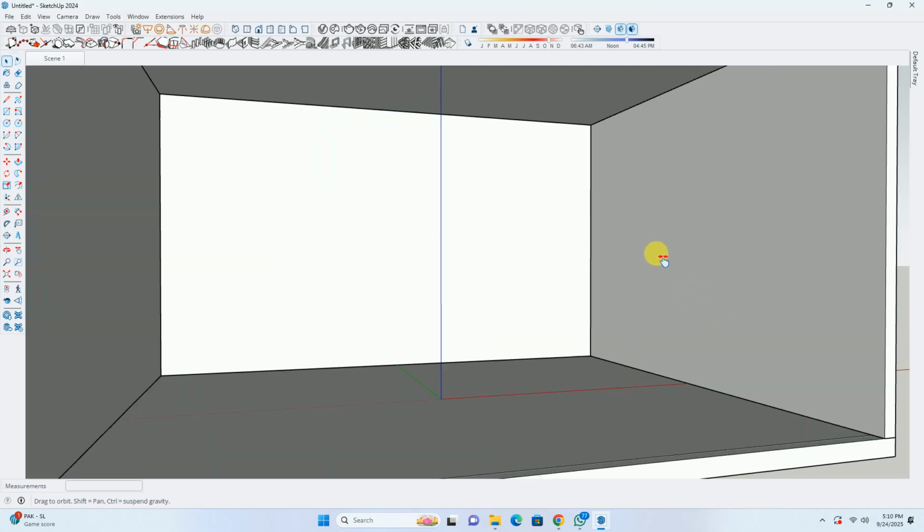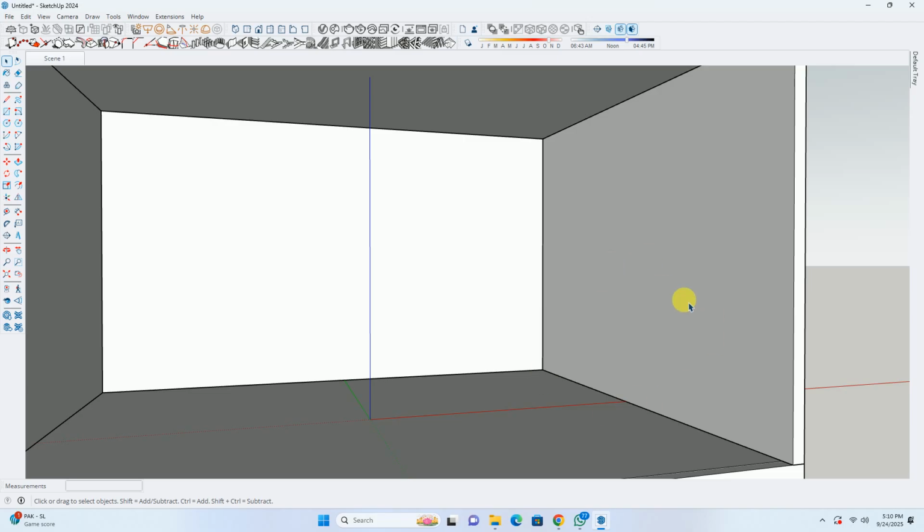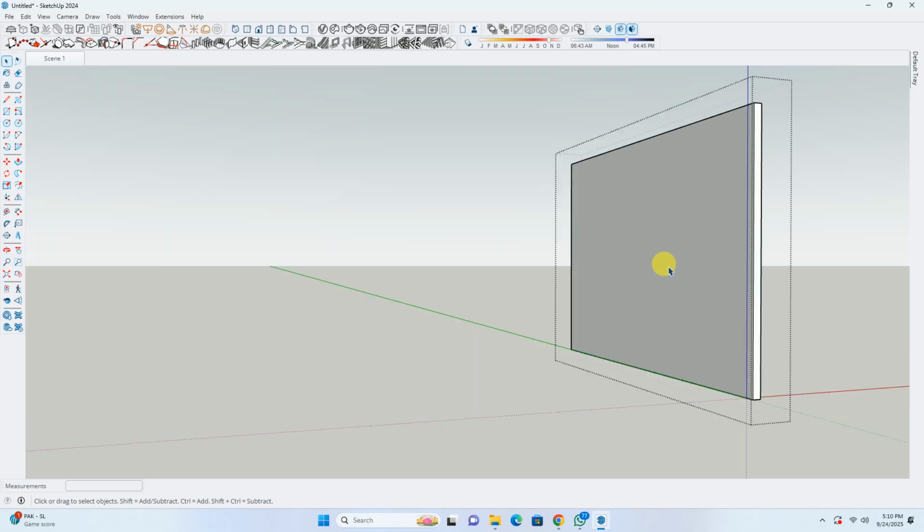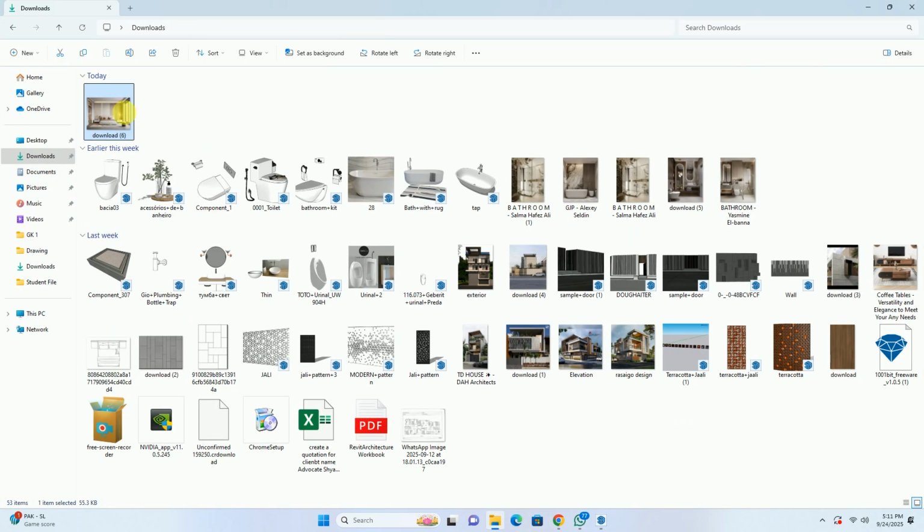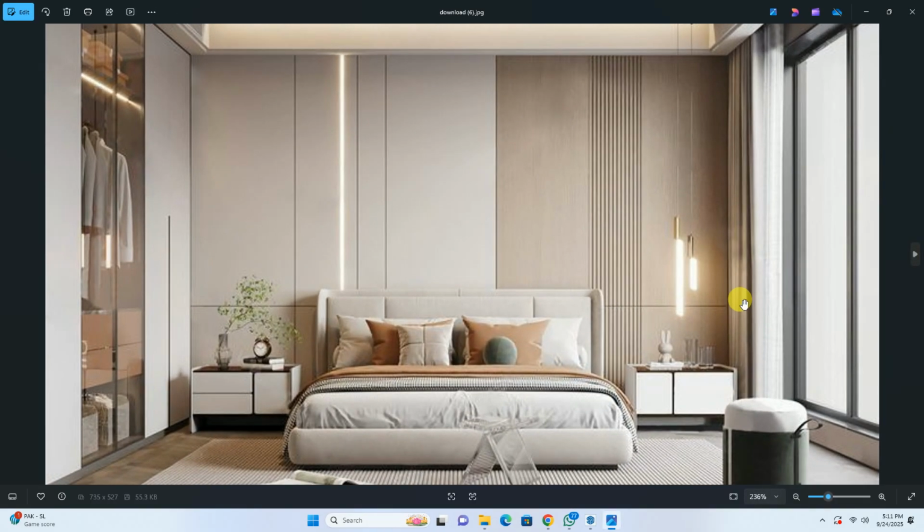Okay. So we want to create a window on this wall. We'll double click on this wall. First of all, we'll have to take up the gap from this wall to this sliding door. It should be at least about 600 mm, so that our sliding panel can get behind that particular gap, and we have a folding gap for our curtains also.